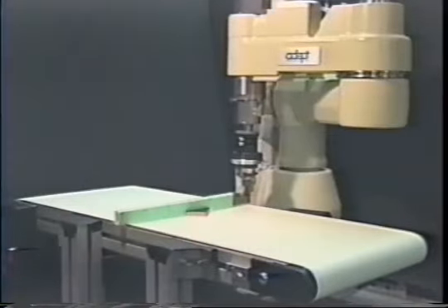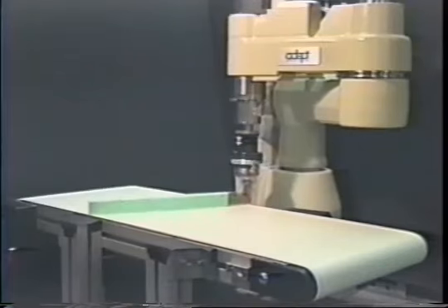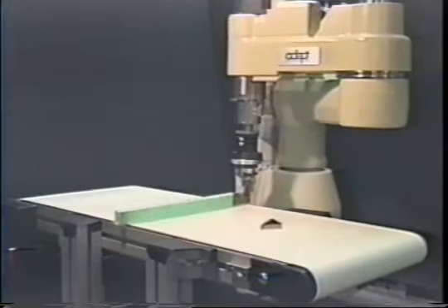Our work explores a simple and flexible parts feeding method for industrial automation. We use just one joint to manipulate the 3 degrees of freedom of a planar part on a conveyor belt. We refer to this approach as one joint over conveyor, or one jock for short. In this implementation, we use one joint of an Adept robot to rotate a fence over the conveyor. A singulated part drifts down the conveyor and comes to rest against the fence.